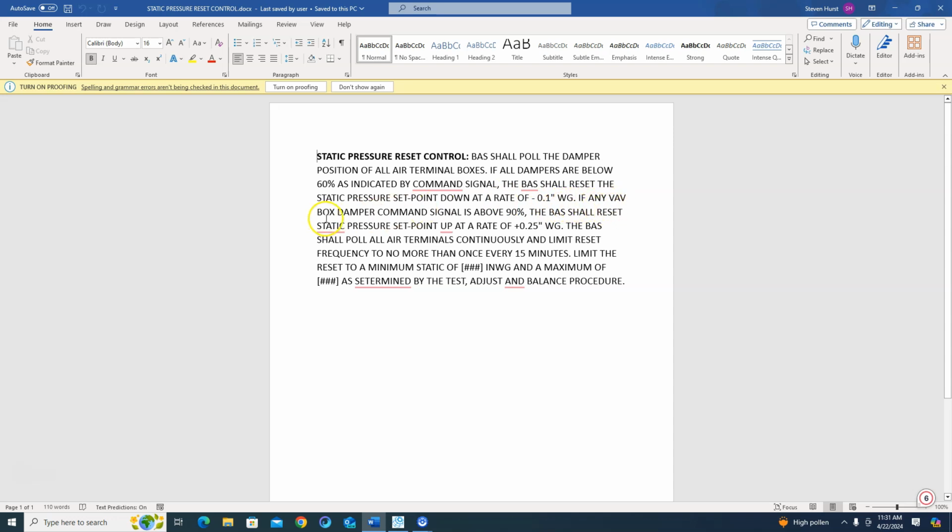If any of the VAV boxes are above 90, we're going to reset up at a rate of 0.25 inches. So if they're in between this, we're not going to do anything at all.